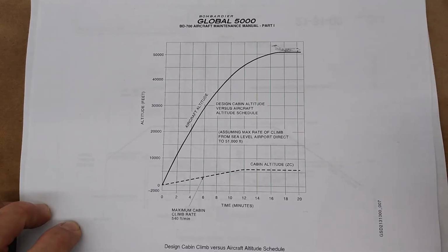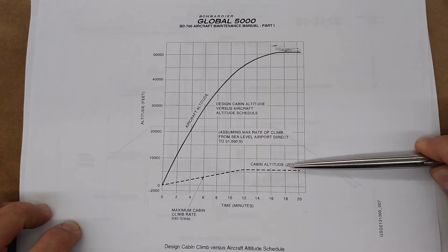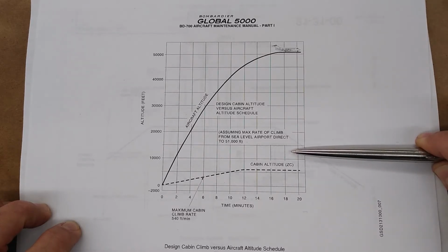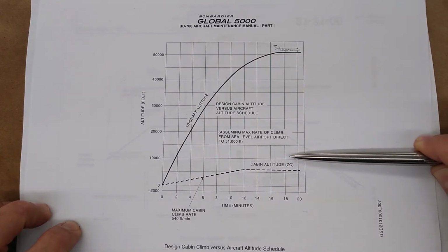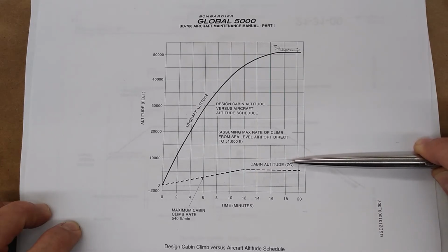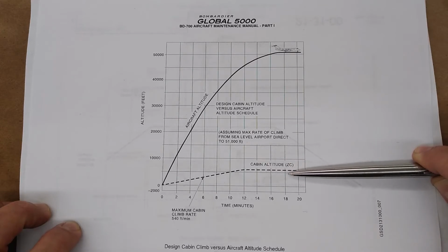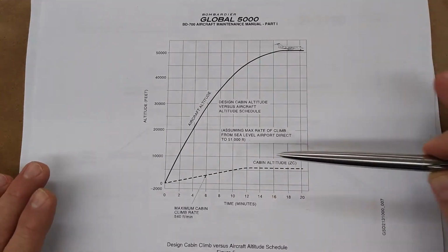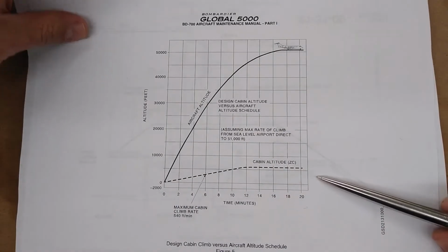That is where they keep the cabin pressurized. You can dial that pressure down a little and lower the pressure, therefore being the equivalent of flying at a higher altitude, and you're going to feel drowsy and sleepy. That's from lack of oxygen. You can increase the cabin pressure, decreasing the cabin altitude, and now you're back in the game. Now, I hope that makes sense.